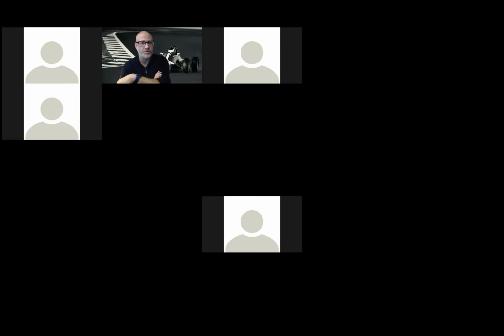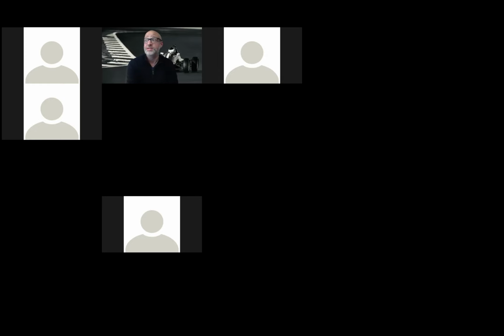Over time, new ECU mappings get added to Race Studio 3. And you can actually see it in Race Studio 3, because there's constantly a little update in the top right-hand side with a little green arrow that is downloading new ECU mappings to be able to use. So I think there are elements of by request, and I would definitely work through that as needed for the particular vehicle.